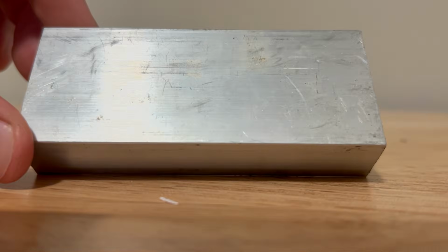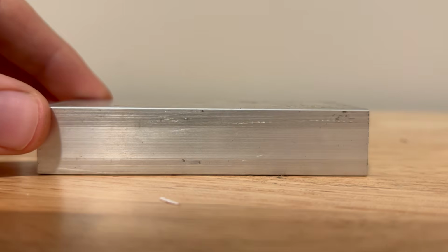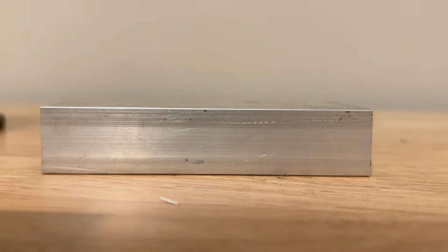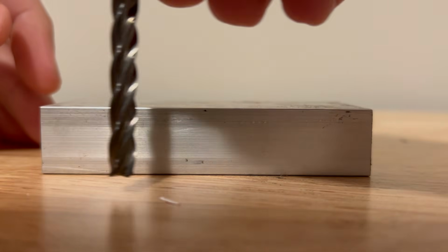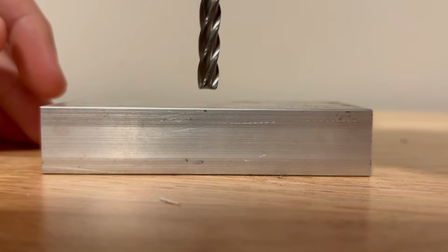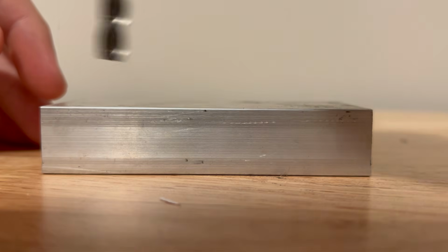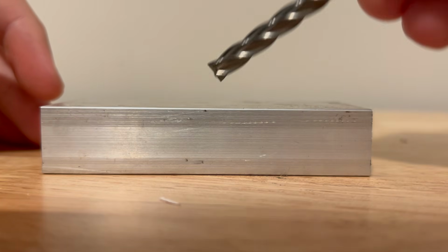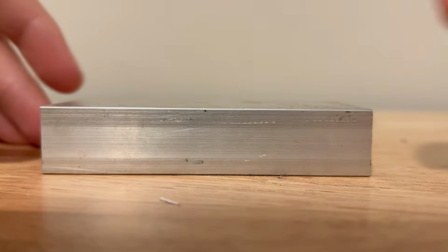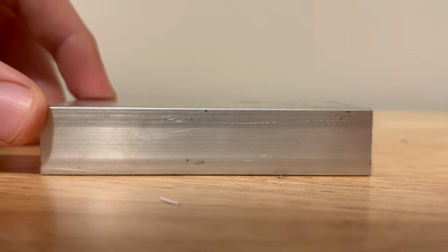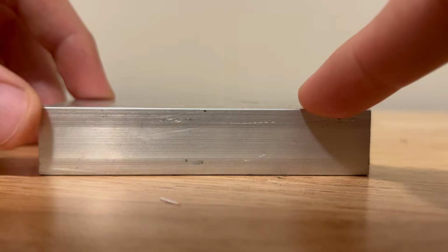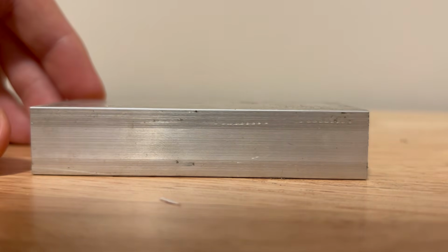So let's take this block of aluminum and explain different tool types that make different features. As we all know, if you want to drill a straight hole, use a drill. If you wanted to profile the side of this part into a specific profile, or make a slot, rough down the top, whatever, you would use an end mill. If you have sharp corners, or you want to countersink, chamfer, anything like that, you would use a chamfer mill or countersink tool, depending on the application.